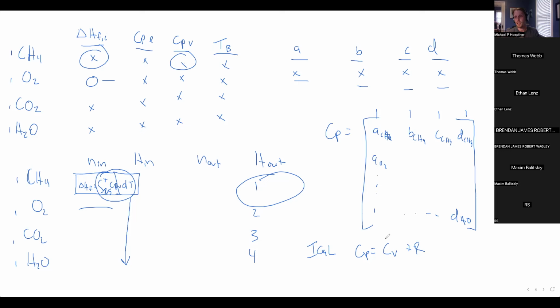So the expression you want to look for is the isothermal compressibility. That basically tells you how the density changes with respect to pressure at constant temperature. And then you can unpack that just the same way that we unpacked C sub P. And then you can estimate how much the density of a liquid changes when you change its pressure a certain amount.